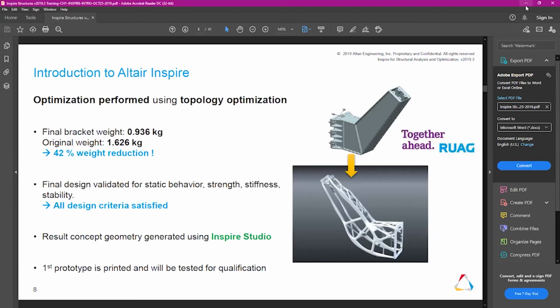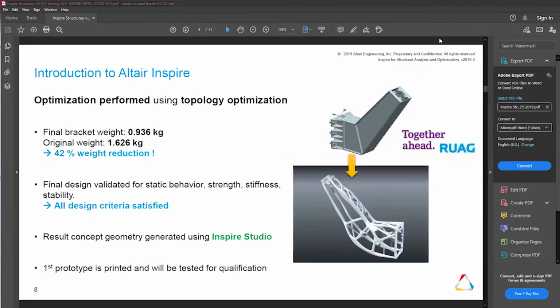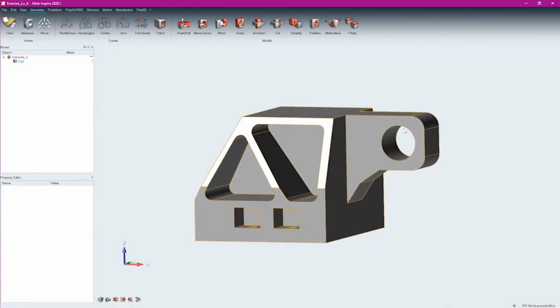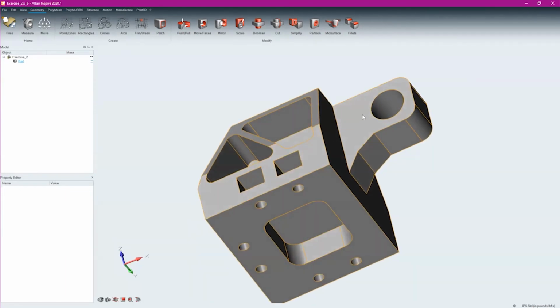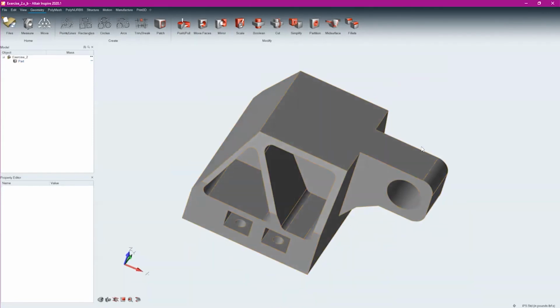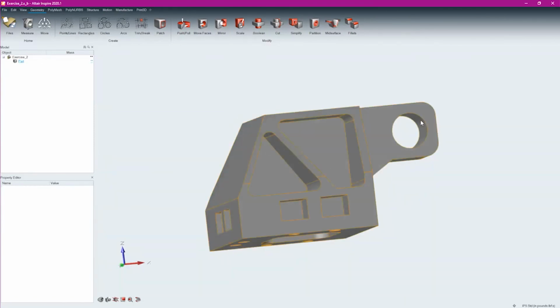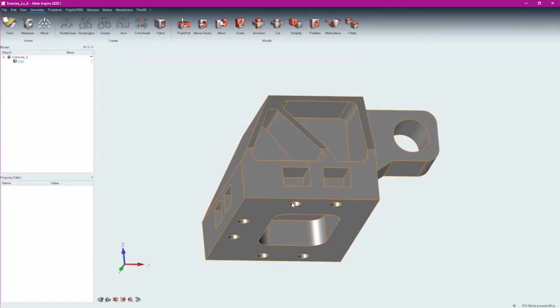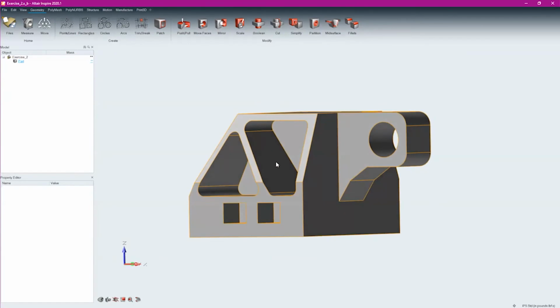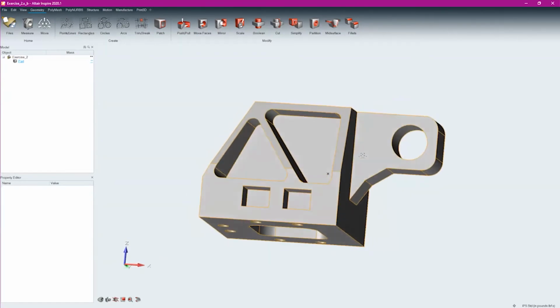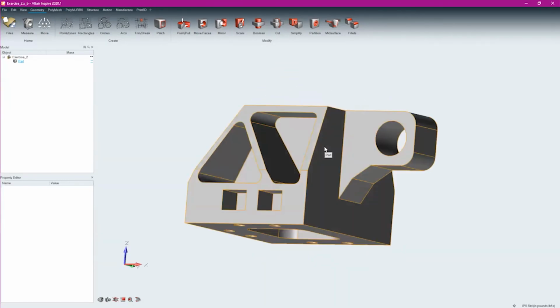If I want the best, most optimized, lightest part possible, I'm going to take a chunk of material and determine what of that chunk of material is necessary. And to do that, I need a good chunk of material, because the solver is going to analyze where the load is and how the load passes through the part to the constraints, and make sure it's got material there. But with my currently designed part, if it wants to get the load from here to this back thing, it can't. Because this part has been designed and because they put some lightweighting features in it already, there's no material to go through. So optimizing my currently designed part is almost exactly like trying to carve a statue from a statue that already exists. And that's not something you're going to do because it limits your ability.